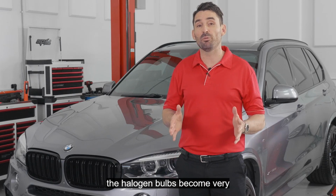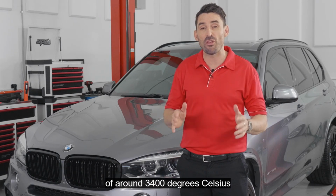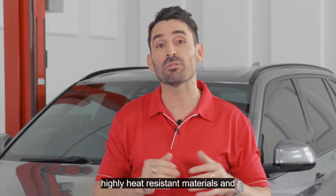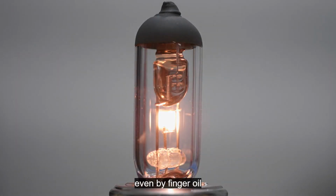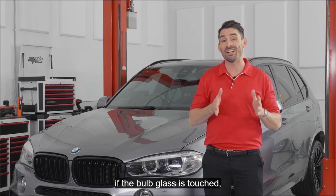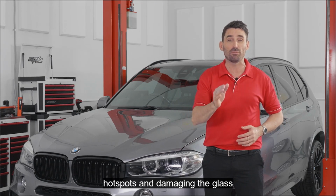However, the halogen bulbs become very hot when in use. The elements can reach temperatures of around 3,400 degrees Celsius. They are manufactured from highly heat-resistant materials, and the bulbs must be handled carefully because they are sensitive and can be easily damaged even by finger oil residue left by fingerprints. If the bulb glass is touched, it must be cleaned immediately to prevent the oil creating hot spots and damaging the glass.